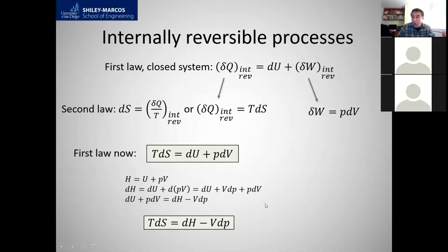Always think of H as open system, U as closed system, like a piston cylinder. When the piston, for example, moves out, you have a portion of the process we call an open system process. In the ideal gas law, dH equals m Cp delta T, and for internal energy in a closed system, we say m Cv delta T. Cv means specific heat at constant volume, Cp specific heat at constant pressure.